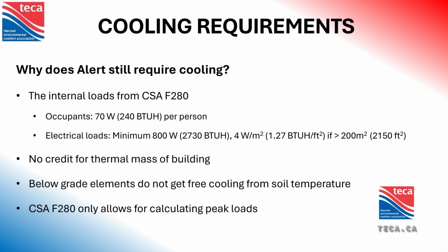Regardless, what CSA F280 is saying is you need half a ton of cooling in there, and it isn't very logical, right? Because what do you do when it's 13 degrees outside and you're hot? You open a window, right? And this is the sort of climate where you can absolutely do that and regulate your heat gain just by passive measures. But we don't get credit for anything like thermal mass. We don't get credit for opening a window.